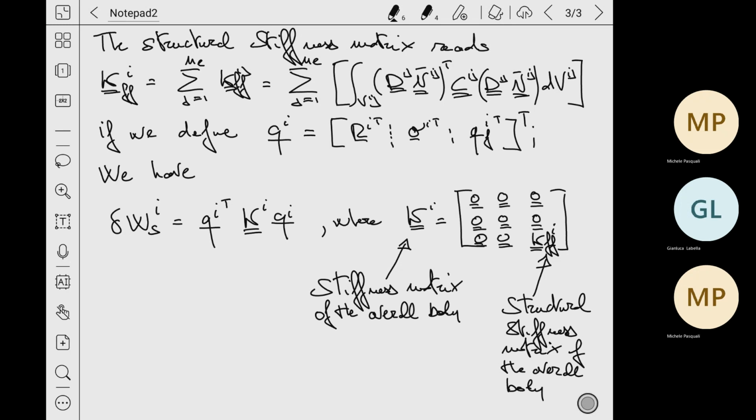As you can see, the stiffness matrix is in general much easier than the mass matrix. And the reason for that is that we are enforcing a floating frame formulation in which the mass matrix encompasses all the effects of nonlinear couplings between deformation and rotation, and in general the rotation and the translation, because your body is moving.